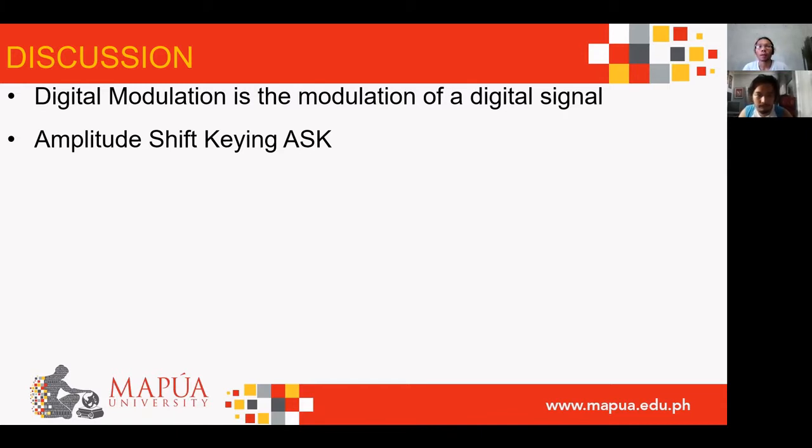Amplitude shift keying, in the context of digital communications, is a modulation process which imparts to a sinusoid two or more discrete amplitude levels, also called on-off keying or OOK. These are related to the number of levels adopted by the digital message. For a binary message sequence, there are two levels, one of which is typically 0. Thus, the modulated waveform consists of bursts of a sinusoid. In the next figure, we will see the binary ASK signal, where the lower is 0 and the upper is 1 in the binary sequence, and neither signal has been band limited.